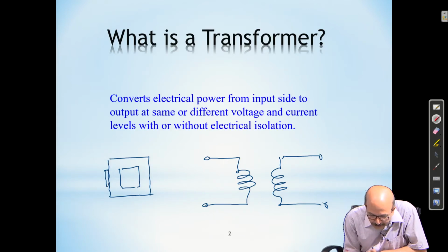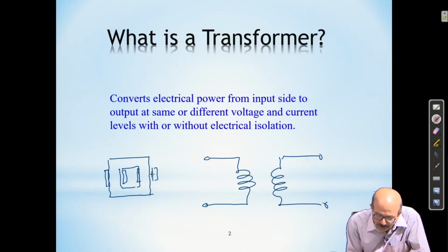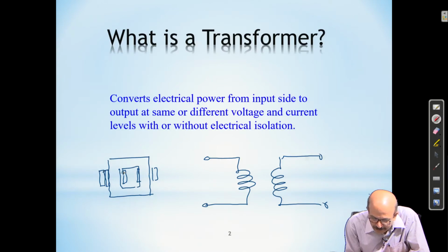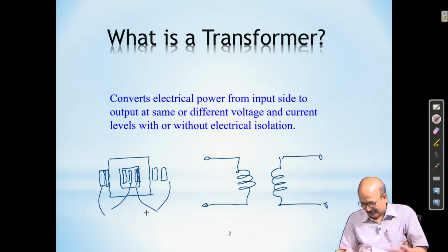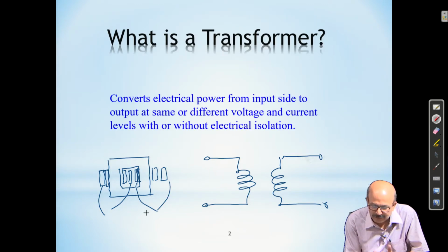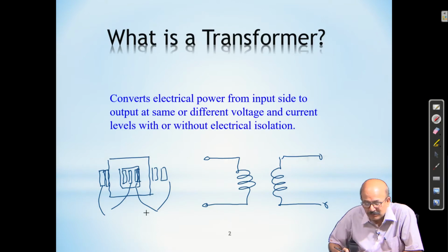You have part of the low voltage coil first, and then the remaining part of the low voltage coil here, and then on top of that you can have, say, the high voltage coil this side, and then the high voltage coil this side. So, you can see that these are high voltage coils. You can think that half of the high voltage coils are on one limb, half on the other. Why is it done like that? To make leakage minimum. This is a typical core type construction.